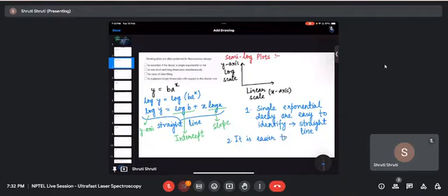So how do we calculate temporal resolution? It is the given TAC range divided by the number of channels. If you do that, we get 25 picosecond. That is the temporal resolution, the minimum time which you can resolve. So from the given options, I'll do the same thing: TAC range divided by the number of channels.